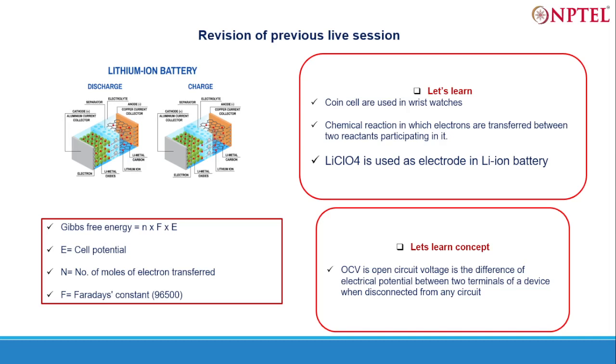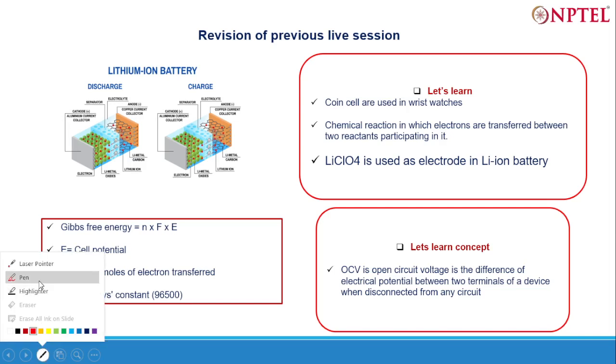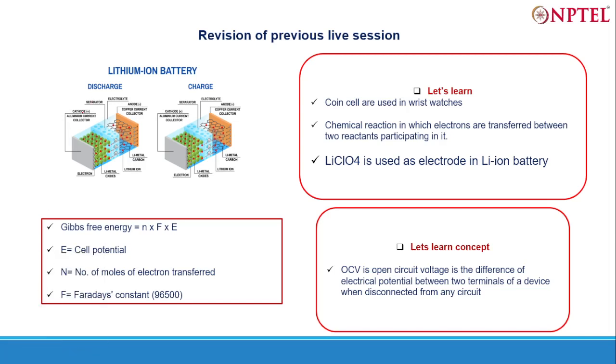See, I will give you a basic introduction about this. A normal nickel cadmium or lead acid battery, you take, is basically 40 or 50 watt hour of energy density per kg. But lithium-ion batteries are so energy dense, they have an energy density of 5 times that of a lead acid battery.